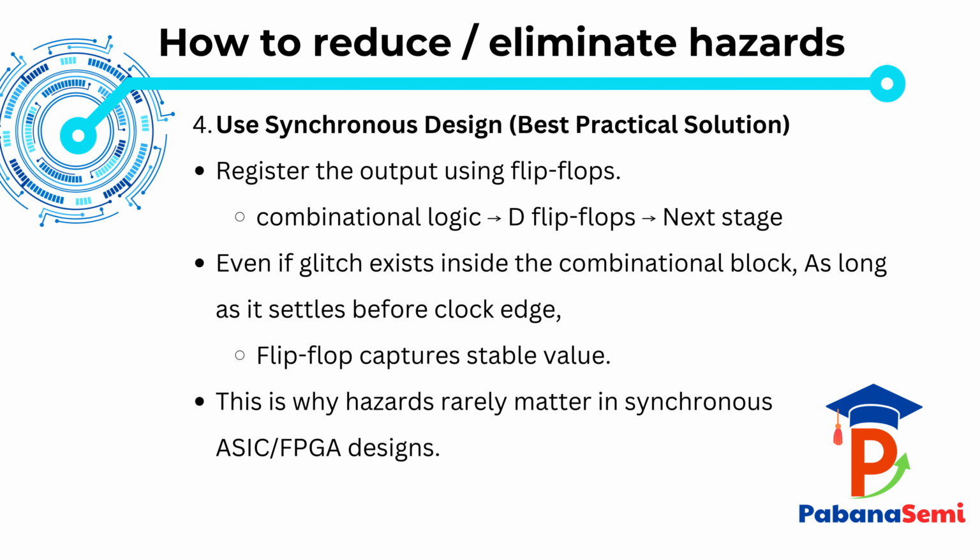Let's look at the most practical and widely used solution to handle hazards: synchronous design. In synchronous systems, we don't rely on raw combinational outputs directly. Instead, we register the output using flip-flops. So the structure becomes combinational logic, D flip-flops, next stage.